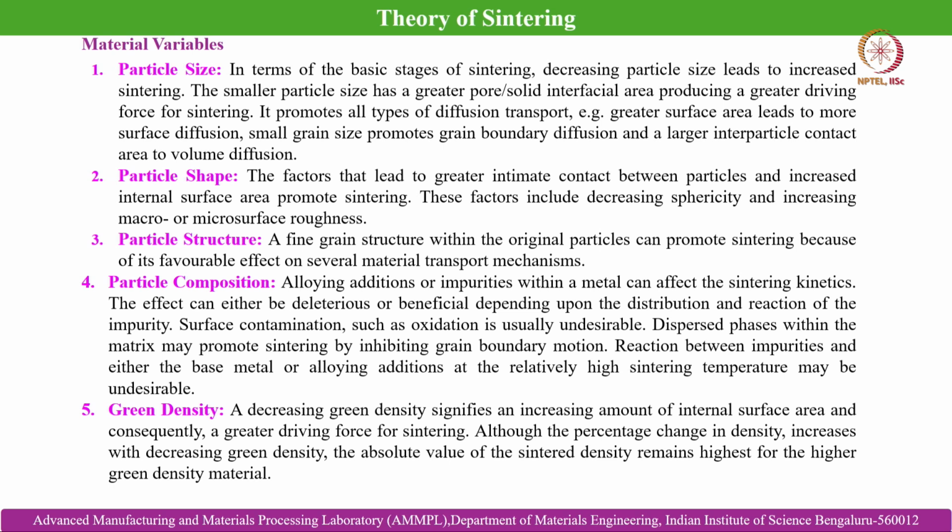The smaller particle size has a greater pore solid interfacial area, as I was telling you earlier. It produces a greater driving force for sintering, and it promotes all types of diffusion transport. That is, greater surface area leads to more surface diffusion, and small grain size promotes grain boundary diffusion, and a larger interparticle contact area promotes volume diffusion. So, this is the effect of particle size, and then next is the particle shape.